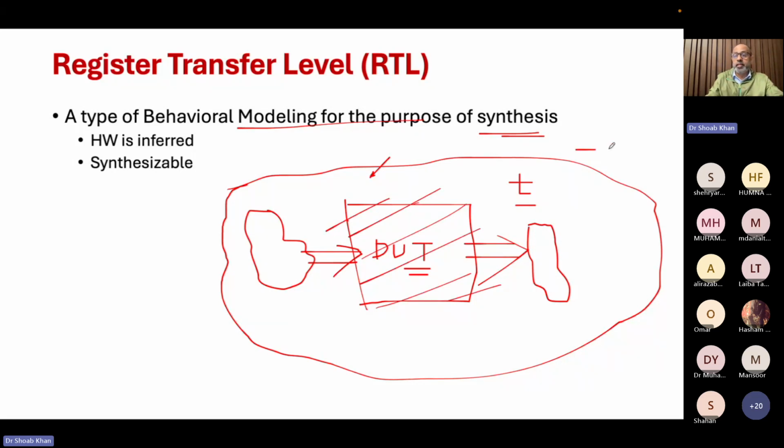For example, even if you are adding two 32-bit numbers and you want every bit to change, it is 2 raised to the power 32 into 2 raised to the power 32, and it'll take you forever to just check that a simple adder is working to your satisfaction. That makes verification very challenging, but at the same time very valuable, because you have to think about how you are going to get the maximum coverage of the code which is written, so that once you tape out and send it to the fab, it is guaranteed that it will work properly.